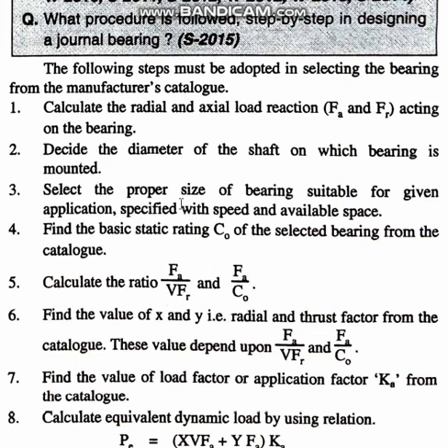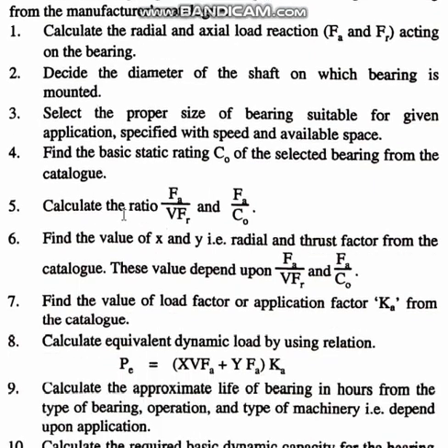Then, for the selection of proper size of the bearing suitable for the given application, what is the application? It is specified with the speed. What is the speed? And what is the available space? On the basis of the application, the speed of operation, and the space available, you have to select the bearing from the catalog.